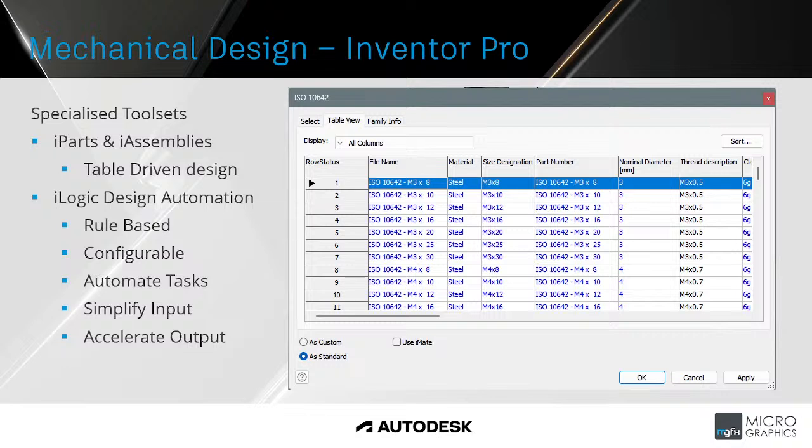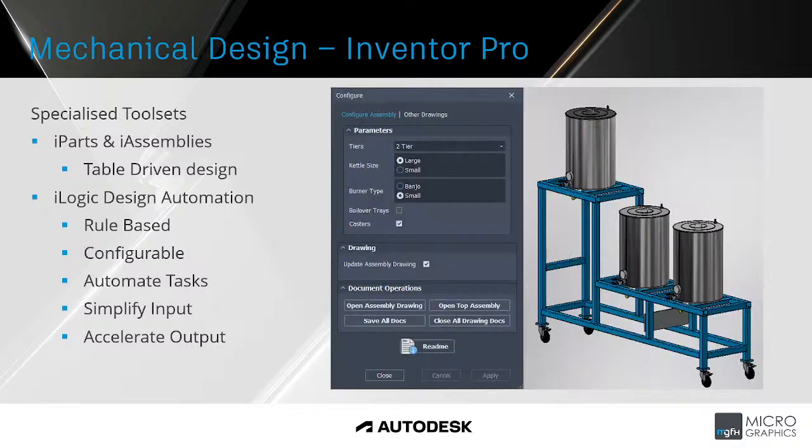Very similar with assemblies. In the case of assemblies, you can turn components on or off when you go down your rows. And there are other things like constraints that could be changed. But the big part here is the iLogic design automation. With iLogic, you can create rules, very similar to Visual Basic programming. You can create rules within your design that will check things. If you set, in this case, the kettle size to large, the frame needs to be a certain width, and that can update the frame. If you choose small, the frame width and length will change and will update according to that selection.